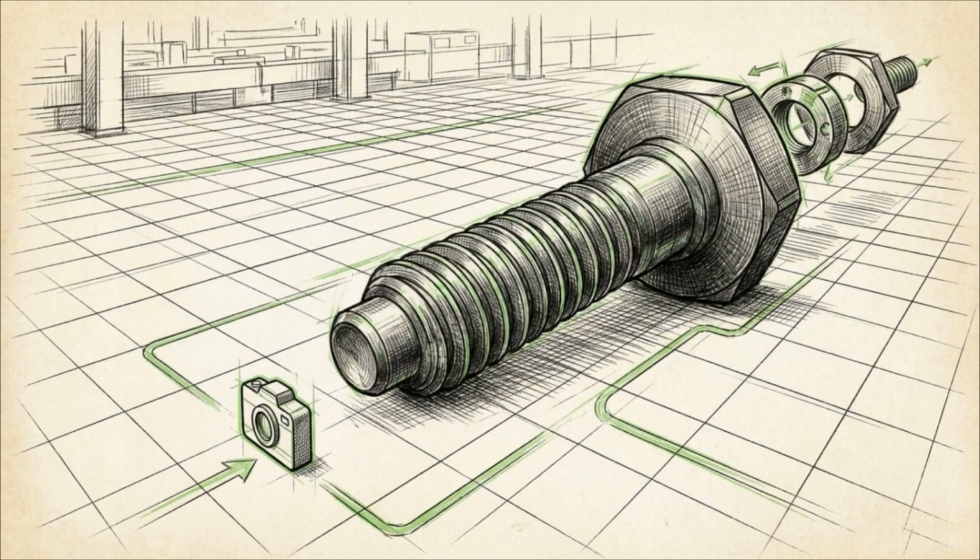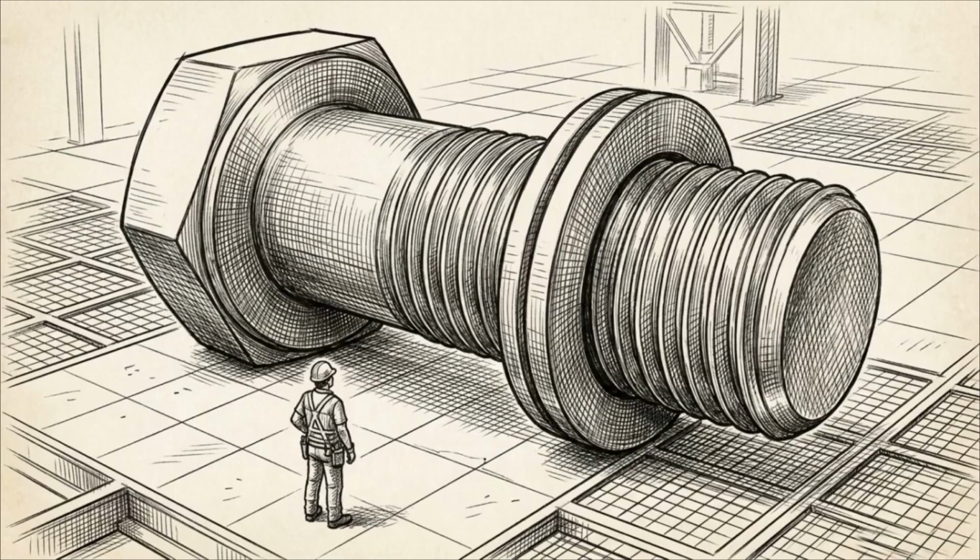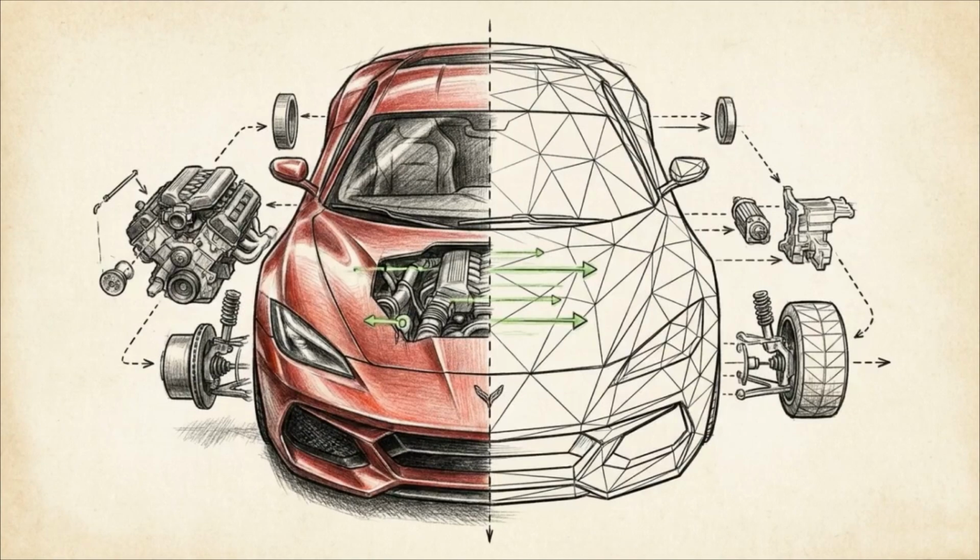The first immediate symptom of this process is the persistent scale mismatch. A factory modeled accurately in millimeters frequently imports into a game engine completely out of proportion. Next comes the total loss of material data and the flattening of complex scene hierarchies.